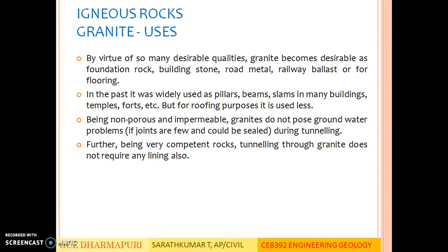Being non-porous and impermeable, granites do not pose groundwater problems during tunneling. Since the joints are few and it is not a very porous material, water cannot enter it, and it is very suitable for tunneling purposes. Further, being very competent rocks, tunneling through granite does not require any lining also.